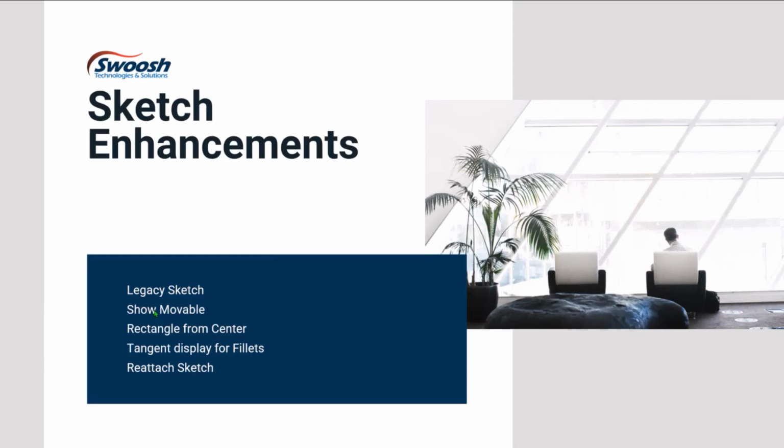The other enhancements I'll show here in this section of the presentation deal with specific enhancements within the sketch tool. There's the feedback you get, the visual feedback that you get when you work with sketches that have conflicting definition, I'll say constraints, just because that might be more recognizable from past history of working with NX sketches. So when you go through and work with some of the settings like the show movable option, it'll highlight for you some of the conflicts that you might have.